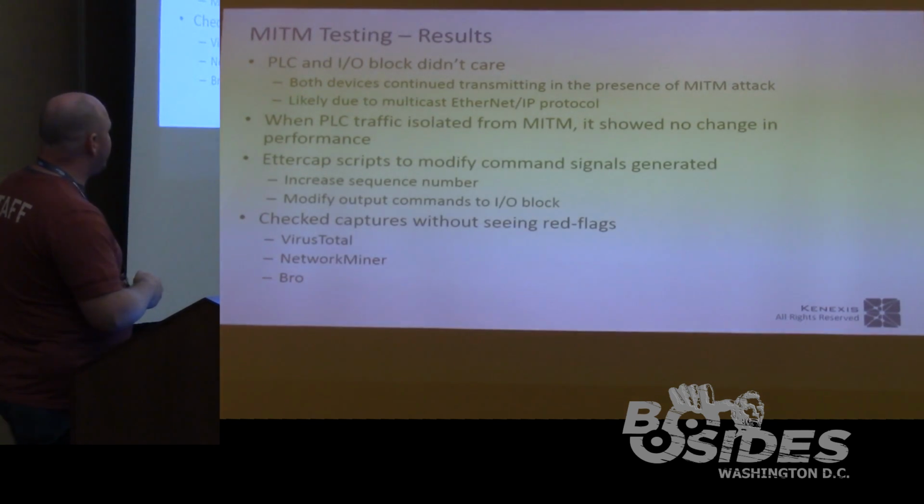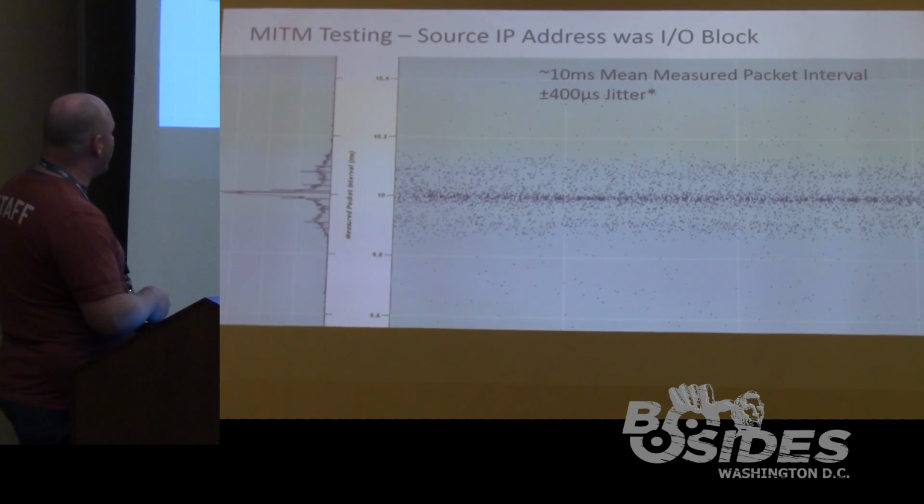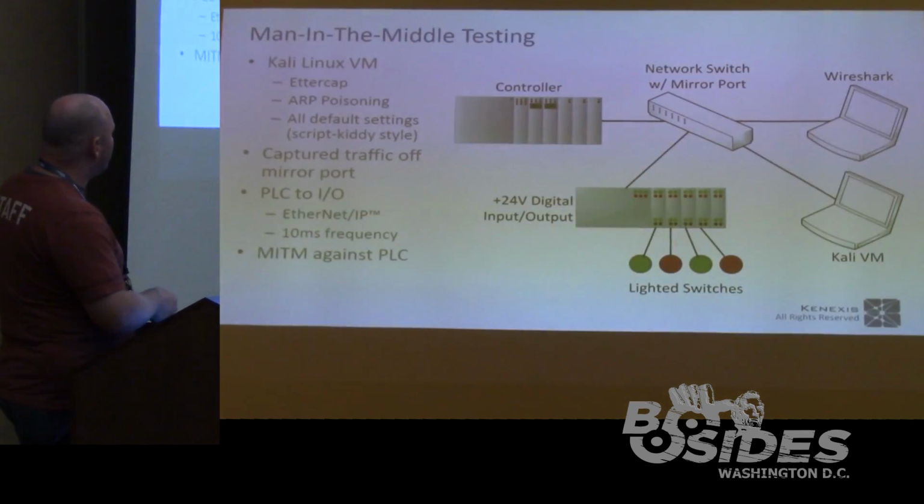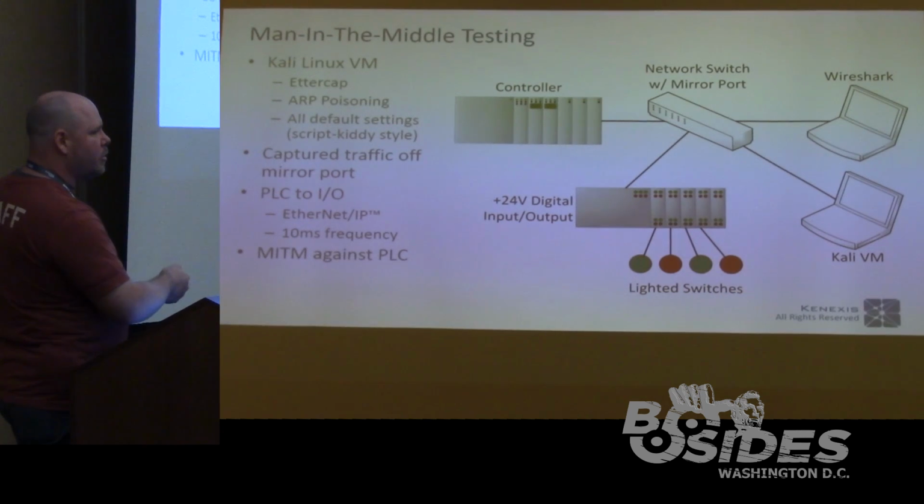And this is likely due to the fact that this protocol actually uses a multicast signal for this. This device transmits over multicast back to the controller. And that's for performance reasons, because it could be talking to a controller, an HMI, or a historian, and you don't want to send three individual packets out there.